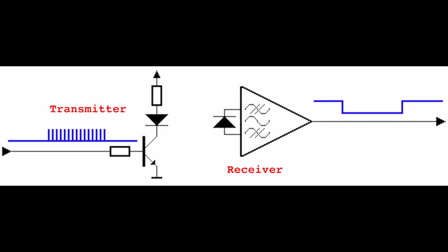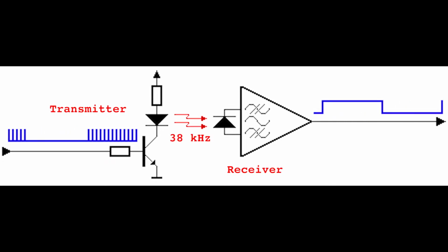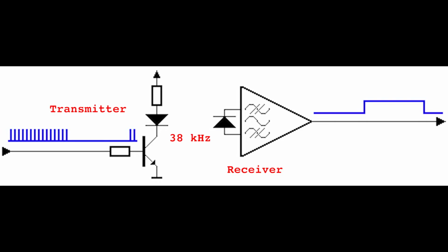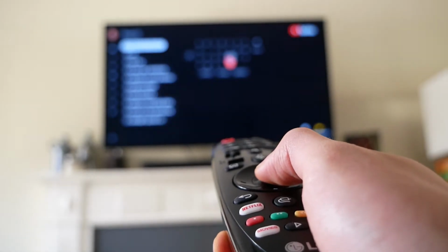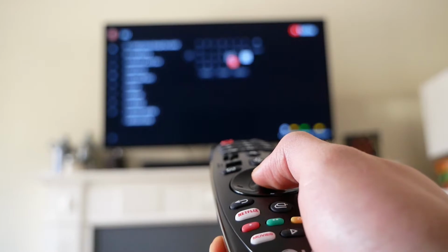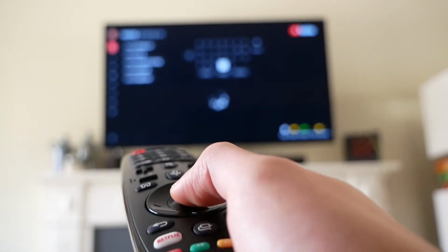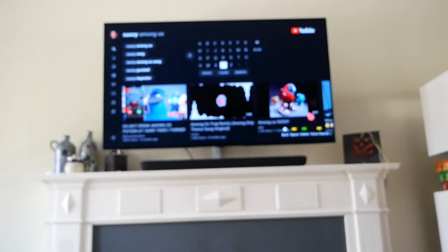Signals from the transmitter are modulated, most commonly at 38 kHz, to differentiate between the remote signal and ambient IR. The receiver then demodulates the signal into a binary waveform and is then read by a microcontroller to ultimately perform a certain function. Different buttons on the remote send out a unique series of highs and lows to distinguish between buttons for performing a variety of activities.